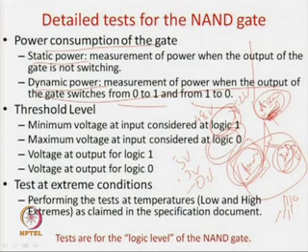For all the ones, your voltage level should be within 4.8 volts to 5.8 volts, and for 0 it should be within say 0.3 volts. You have to measure all these using analog techniques, because digitally we cannot measure volts, and then find out that the voltages at logic 0 and logic 1 are all meeting the requirements. So, your logic 0 and logic 1 are compatible with the input voltage ranges.